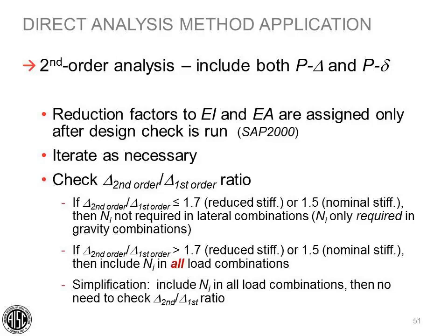Even in the old green book, if that's what you're using, the 9th edition, stability is still required to be considered. And even back then, we were running P delta analyses on most of our buildings. So it will result potentially in more conservative sizes if you have flexible frames.